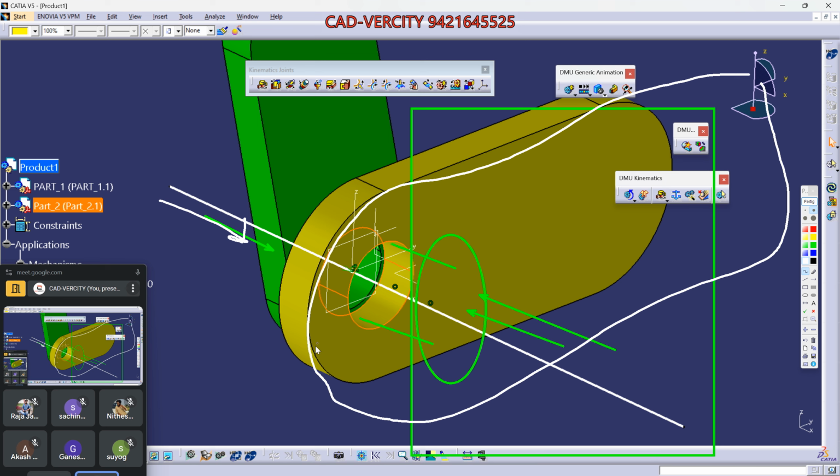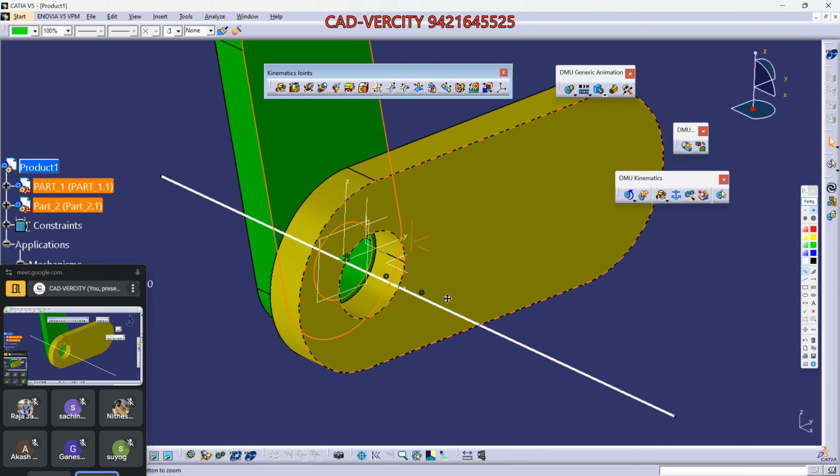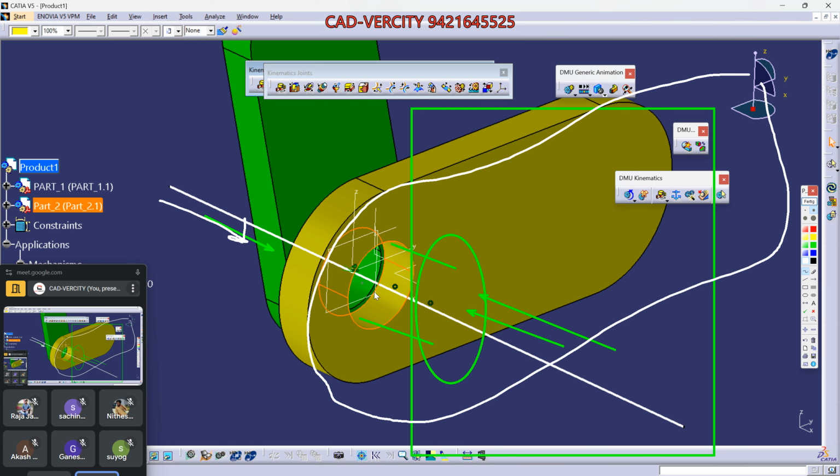Okay, so while starting your design you should think about everything. If you are using any revolute joint over here, I will need some metal part, or there should be a rivet, or there should be a nut and bolt. But sir, we can't install that nut and bolt from this side. Why, Ganesh? Because there is a metal part over here, so we don't have any access from this side.